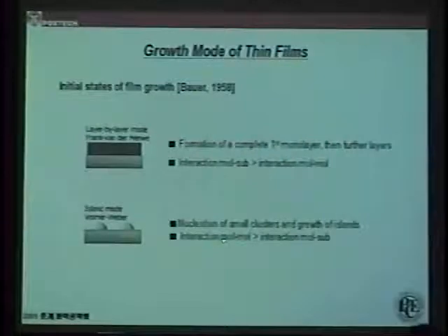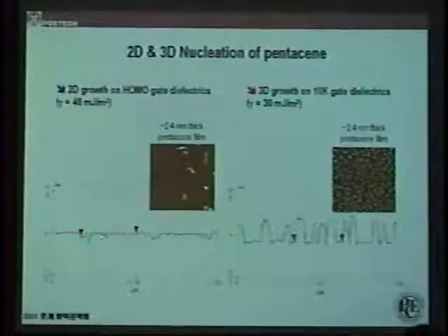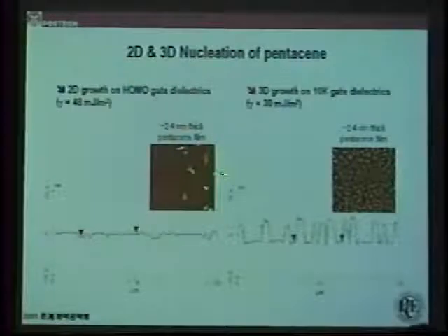And in the case of the silicon modified one, the surface energy of pentacene is higher than the substrate. So the pentacene cannot cover the whole surface. Then we just have a droplet state, forming an island structure like this. This shows the AFM morphology, showing that most of the surface is covered with pentacene, and this white part is the uncovered one. It's quite the opposite.